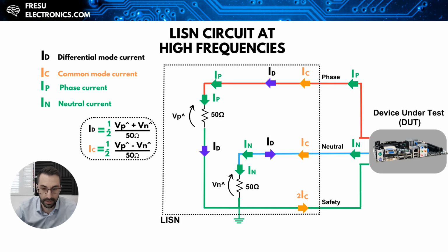One important aspect here is that the differential mode currents we observe are not functional 50 or 60 Hz power line currents required for the normal operation of the device. And also the common mode currents returning through the green wires are unwanted and are not typically intended as a part of the design. And this is crucial because the green safety wire is intended as a safety measure when a fault occurs. So this is not meant to carry currents during normal operation. And therefore, when the green wire carries current, as in this case with high frequencies, which is carrying common mode currents, it can result in the failure of the regulatory standards.